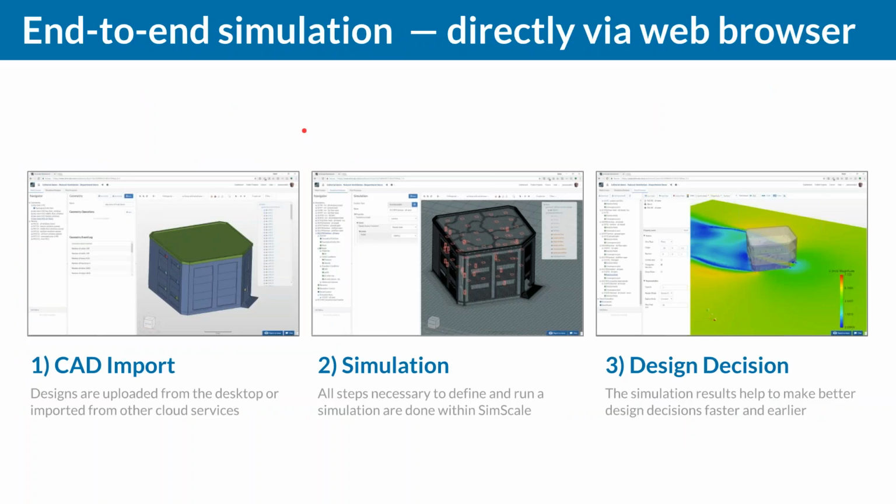All right, now let's take a look at the end-to-end simulation workflow when you want to use Rhino together with SimScale. And this is, again, very similar to what we discussed yesterday. So first of all, you need to import an actual CAD model of your building. And that's maybe the first difference, because especially when it comes to including the external flow, we have to make sure that we have a closed volume model. So the walls need to be closed, and as I mentioned, they need to have a defined thickness.